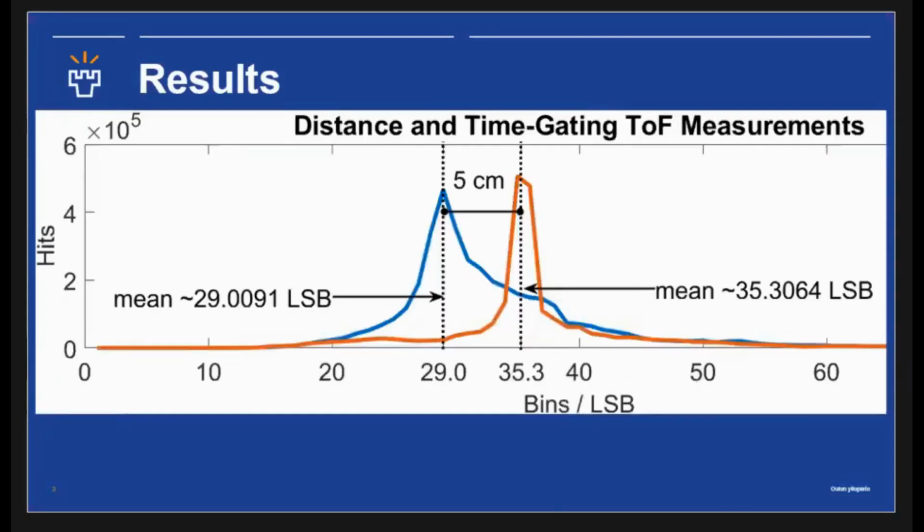To resolve the average width of the bins, the laser pulse was emitted onto a matte surface, which can be adjusted in distance from the chip. In this picture, 2 pulses were sent, 2 measurements were made, and the distance was increased 5 centimeters. Calculation based on the weighted LSB suggests that the average width of the bin is about 52.5 picoseconds.